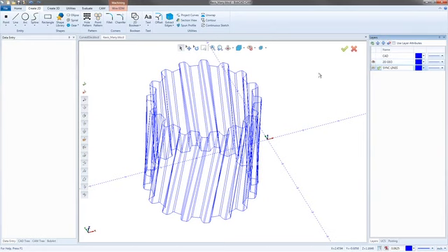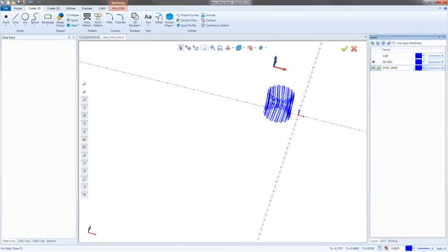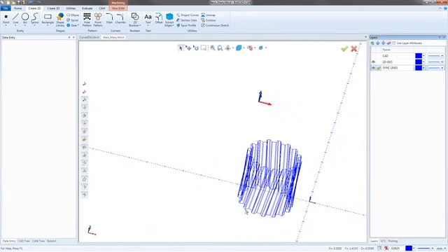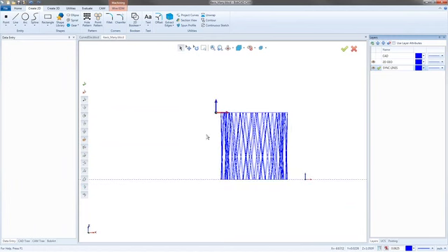So with the sync lines, I'm able to go in and actually tell BobCAD that at certain positions, so each one of these lines, like this one here, when the top guide gets to here, the bottom guide should be down here. So we're using this to kind of cut that whole thing. So I'm going to go to a front view just by hitting Control-2 on the keyboard. And then I got my select tool already. And then I'm just going to drag a box right through the middle of this.